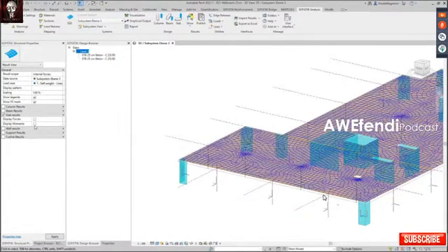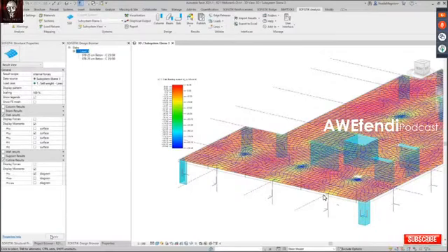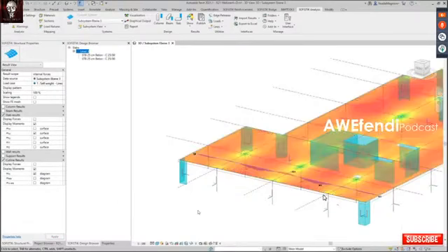Well, you have standard results. Slab results, for example, display the bending moment in different directions. You can decide if you want to see the legend. And because I defined a cut line earlier, I can also display cut line results, which is really nice. You can also play with the scaling to see better how it looks.